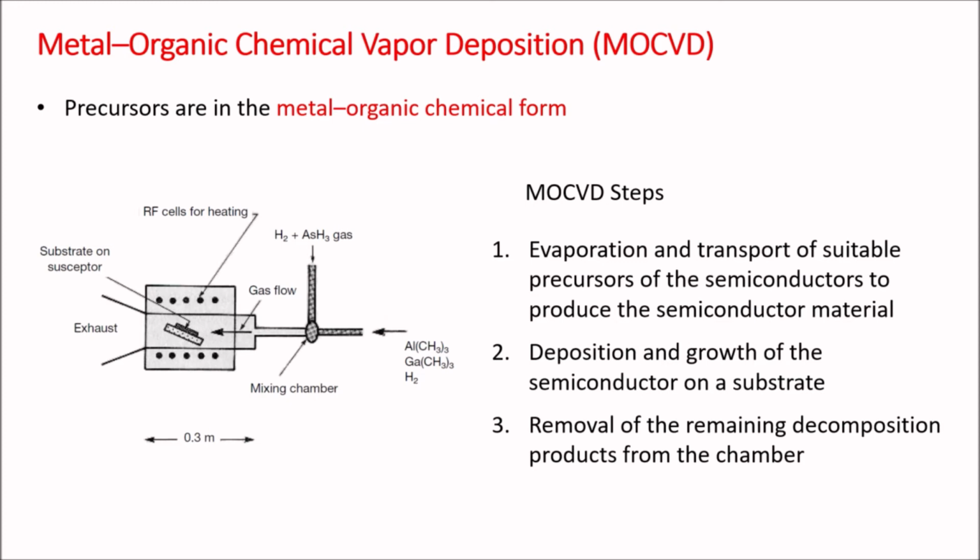Metal organics are a class of compounds consisting of metal ions or clusters coordinated to organic ligands. When the MOCVD method is used for the epitaxial growth on a substrate, it is also called metal organic vapor phase epitaxy or MOVPE. The mechanism of an MOCVD technique is very simple. MOCVD relies on the gas phase transfer of the material to be deposited on the substrate. The deposition ultimately occurs via a chemical reaction at the substrate surface and typically results in high quality epitaxial thin film deposition.